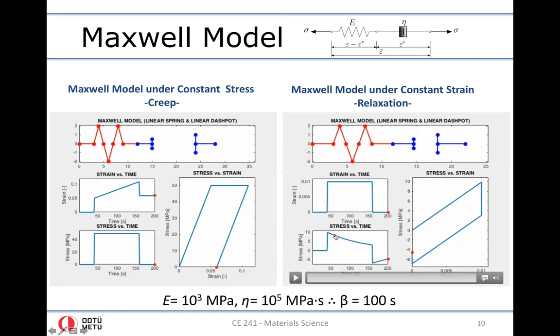For the relaxation time, on the other hand, you could actually do what we have just discussed. You could draw the tangent to the stress time diagram at t0, which is 40, and then find the intersection point of this tangent line with the time axis, and the difference between the intersection point and the point at which we applied strain gives you the relaxation time.